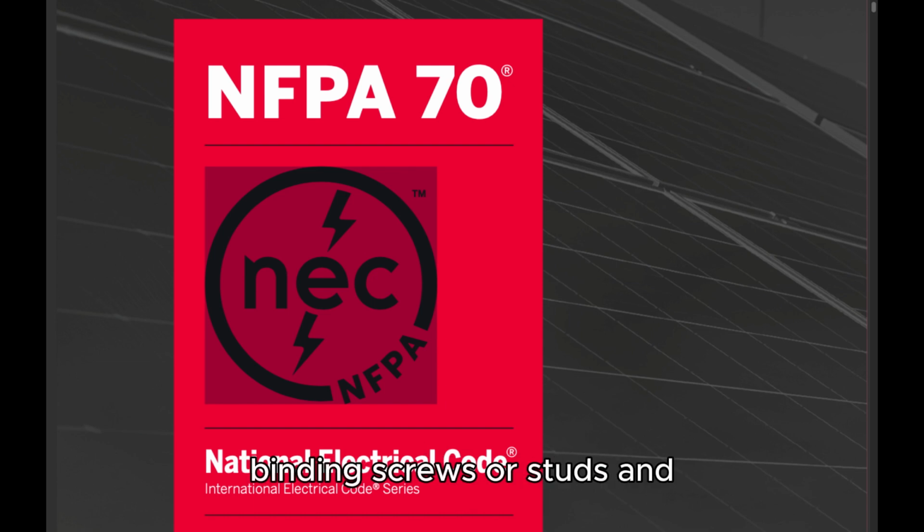Connection by means of wire binding screws or studs and nuts that have upturned lugs or the equivalent shall be permitted for 10 AWG or smaller conductors. Terminals for more than one conductor and terminals used to connect aluminum shall be so identified.